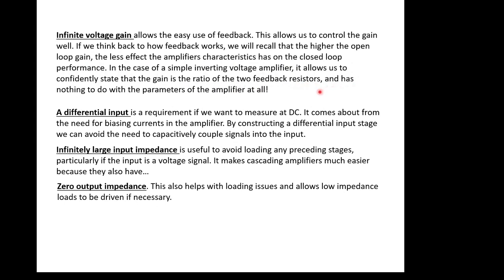The gain of that system has nothing to do with the parameters of the amplifier at all. You can use any amplifier, any op-amp from any manufacturer, pretty much, swap them all out, and it will have exactly the same closed loop gain because it has infinite voltage gain in the op-amp. Okay, so this is a really important idea, and we'll look at that as well going forward.